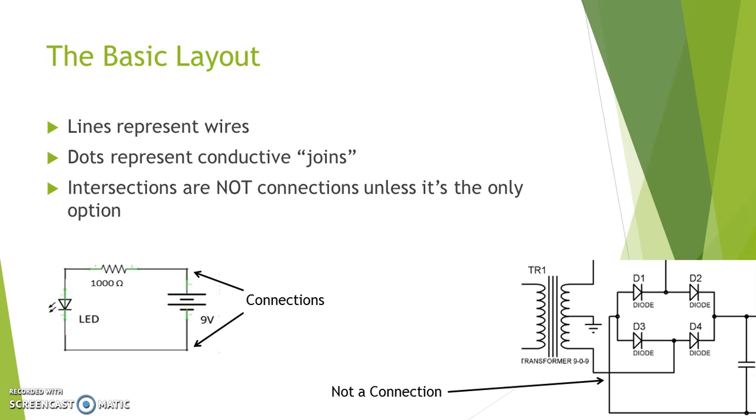This wire is crossing over the other one, but it's not connected with it. In some cases, we'll see a little bump, a little hill that shows that it's crossing over, but many designers don't bother to use this tool. Instead, it's accepted practice to use solder dots as solder joins, and simple crosses are, we assume, insulated wires crossing over each other in 3D space.